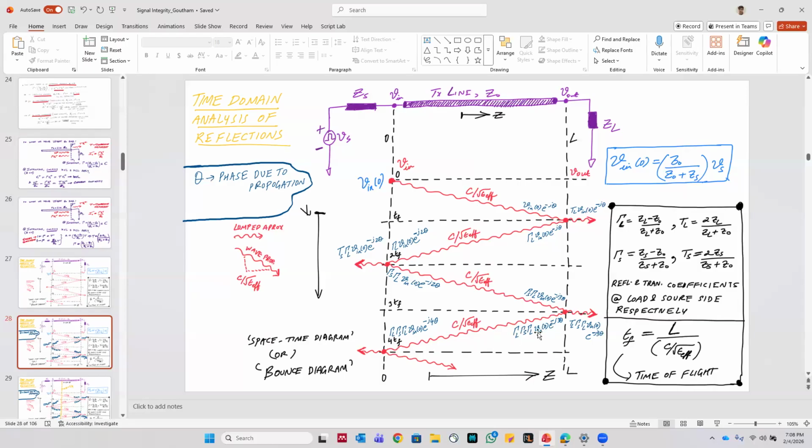So for example, let's take this expression. So what this is telling you is this was the original signal. It had already undergone one reflection at the receiver side, one reflection at the source side, then again one reflection at the receiver side, right? So as you keep going down, you're going to add more and more gammas, right? Also, I don't know how much you guys like to think mathematically, but the more reflections you have, the more gammas you're adding. But remember, gamma is a number less than 1, right? That means if you consider this as an infinite series, since the coefficient is some power of some number that's less than 1, it's going to eventually converge, right? Does that make sense?